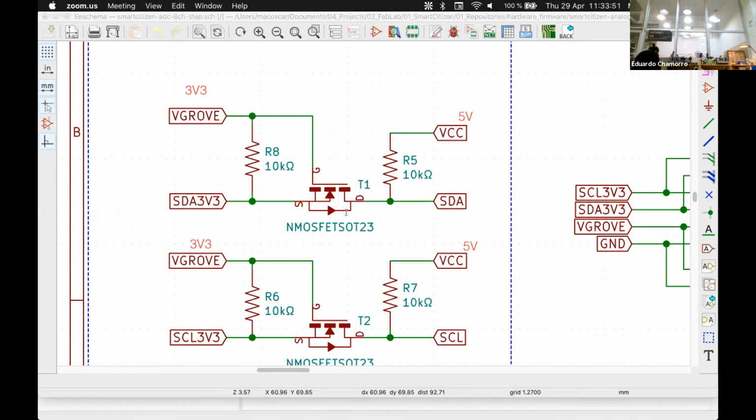But with this setup, you manage to control the opening and closing of the gate depending on this data line or this data line, so that you transcribe this with these 2 pull-ups in both directions. Honestly, this is the type of thing that you read in application notes, and I don't want to say bad things because I don't know exactly how it works, okay? But it does work. It's the general way that these things are implemented.